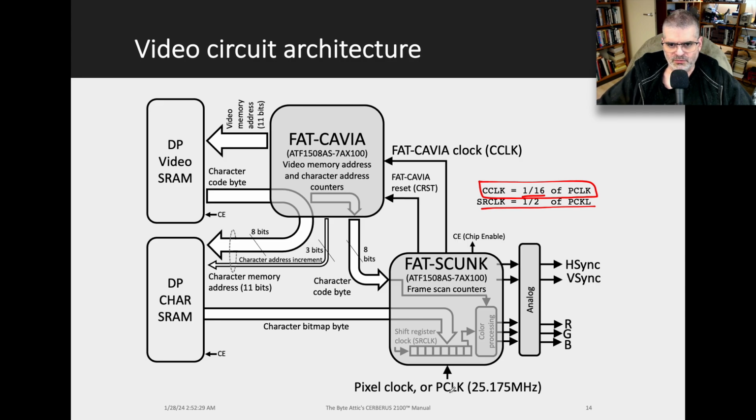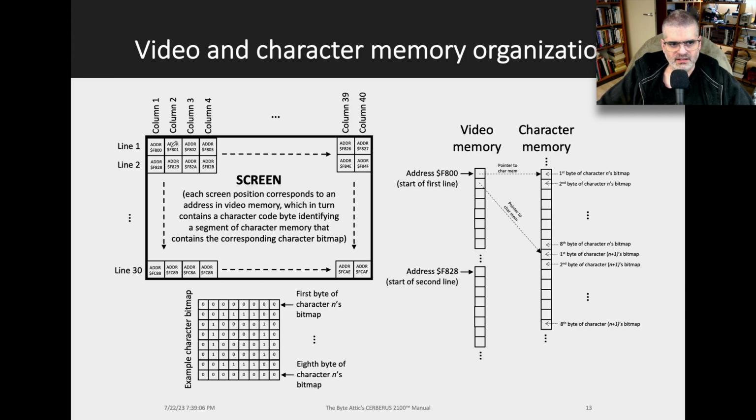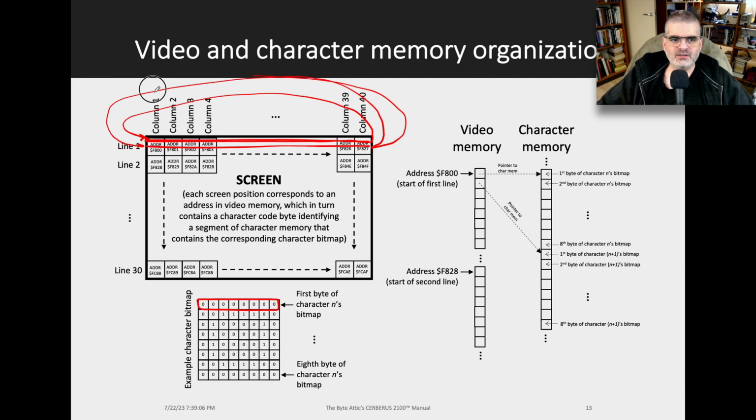And as we've seen before, each line corresponding here to the top byte of each character bitmap on that row of characters will be scanned twice. You will get to the end, come back, and scan it twice, and then print the next row of bytes of the respective character bitmaps, get to the end, and return, and only then go back to the third, and so on and so forth.